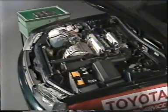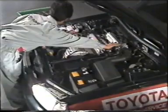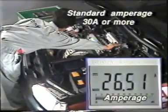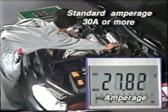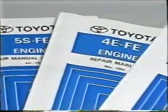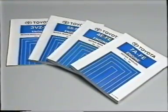If the voltage generated by the alternator is within standard, you can make your final determination of the charging system condition by doing a with-load test. In the with-load test, if the amperage generated by the alternator is at standard or below, you can assume that the alternator is at fault and inspect or repair it as necessary. You can refer to the repair manual for the relevant engine details, how to carry out a test with and without load, and how to determine whether the charging system is otherwise normal or not.